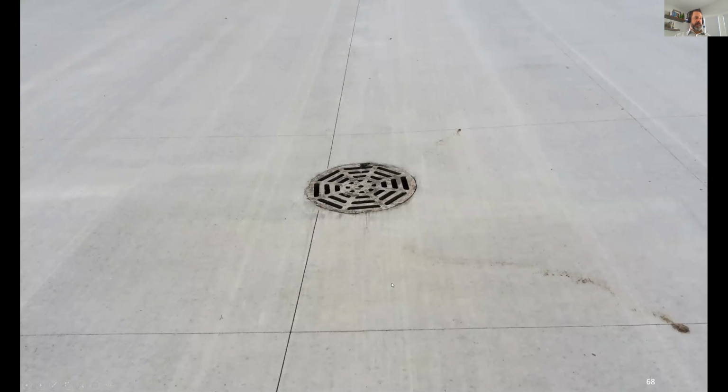The reason for that, I'll go back to what we originally said, is that concrete has its arms around that casting. Think of it that way. This piece of concrete on the right, and its arms are rigid, and in the cold weather, it's going to want to pull away from that casting, and those rigid arms are going to break off as they're wrapped around. And so anything that wraps around is going to crack anyways at this location as this slab wants to shrink and pull away from this joint during cold weather. So this prevents those arms from wrapping around and gives it a spot to pull away that's even.